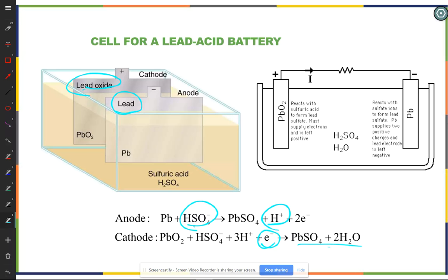And so the chemical reaction will work much slower, which means the voltage is going to drop much more when you're using the battery. And so for checking the battery, you actually want to check what the voltage is under load to see how much it's dropped. So checking it not under load, not really that useful. If your voltage is not full voltage when it's not under load, you know that battery's completely and utterly shot.